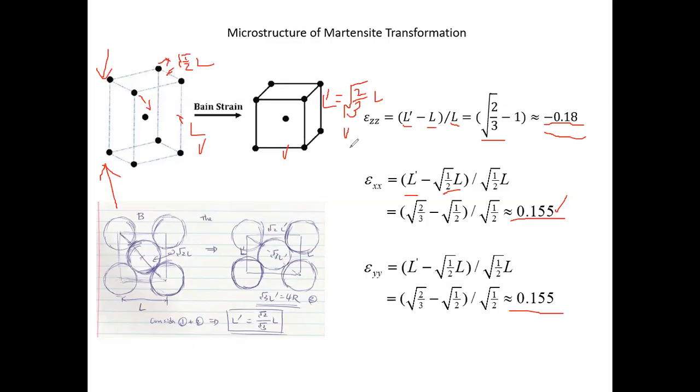Because you have to deform the box, and deform meaning that you have to involve some mechanical energy in the system, right? Either you can apply energy to the system so it has this deformation, or this occurs spontaneously due to the thermal driving force. But this is going to give you a change of volume, right? Which can or cannot be compatible with your original structure, and this possibly is going to contribute to an increase of energy that's going to serve as your barrier.